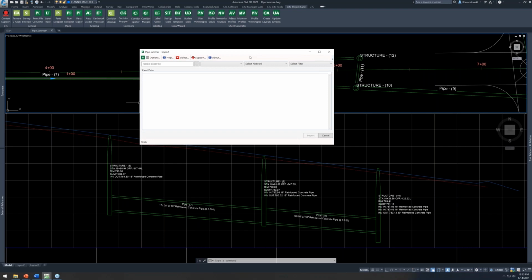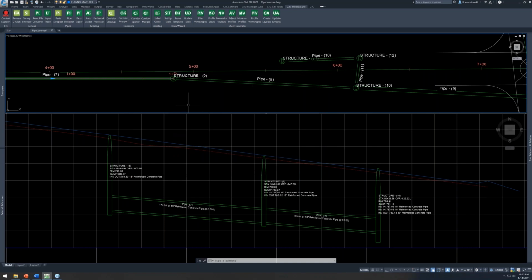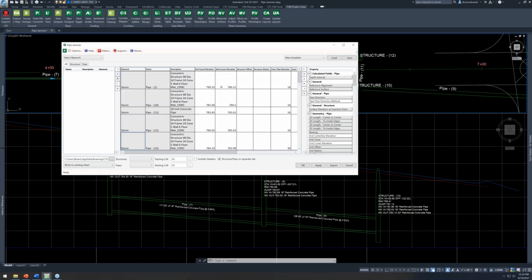If you're looking to create reports, you would use the first utility where you build those out, export, and you've got your Excel spreadsheet. If you want to go to Excel to make changes to your pipe network, run analysis, change sizes, and so on, you use that first module, go to Excel with it, do your work there, and then you come here and write those changes back. Or if you don't want to go to Excel, and this is one of the main things we are after, why are people going to Excel to do a lot of this stuff? Well, because it's so flexible. Well, what we've done is we've basically put Excel right in an in-app interface right in Civil 3D.